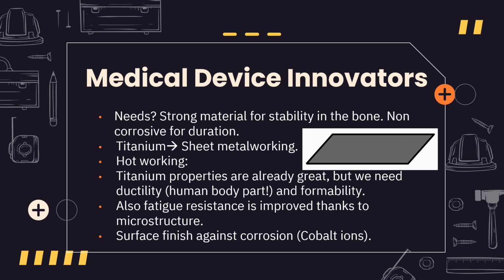And also an important property of hot working is to increase the fatigue resistance by changing a bit the microstructure. We need to take into account that this titanium plate would be inside with our bones for many years, and so it needs to resist for a long time.